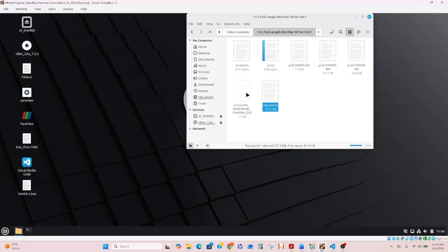For this simulation, since we're using the upper and lower boundaries as surfaces, we don't have to have a surface file. If we had a surface somewhere in the middle of our domain that wasn't part of one of the boundaries, we would have to have another file that's a surface file, and I'll discuss that, I believe, in the third example I'm going to do.